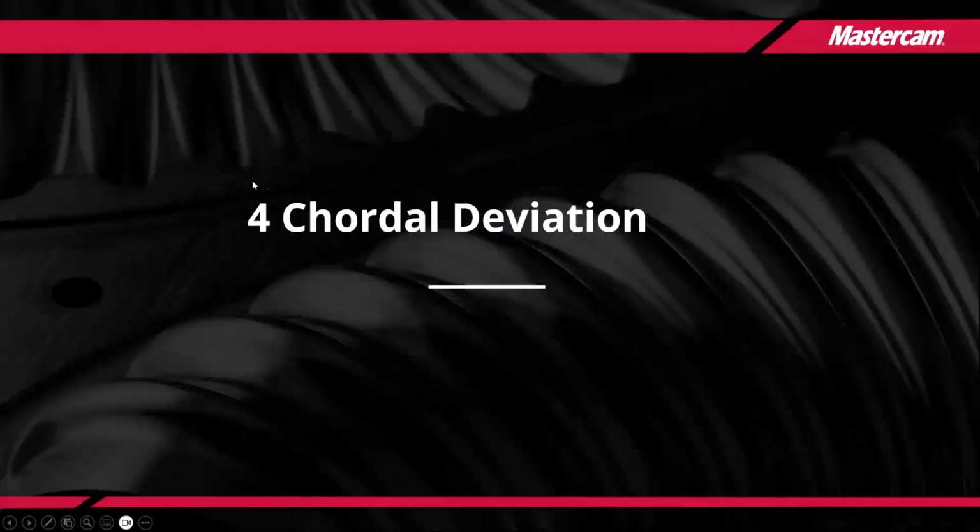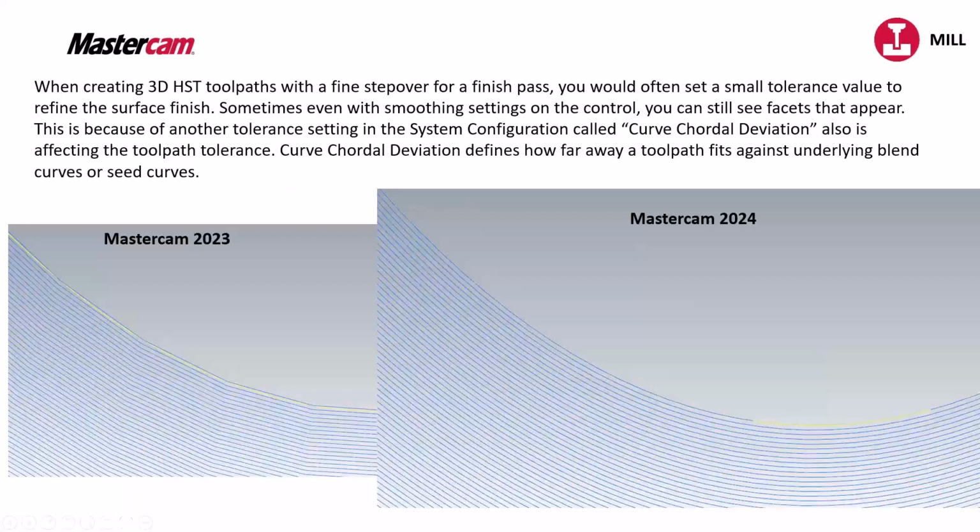So if I go into chordal deviation. In Mastercam 2023 and previous, the setting for chordal deviation was actually in the configuration.